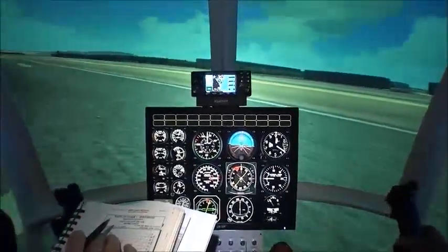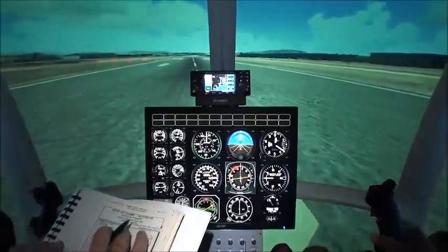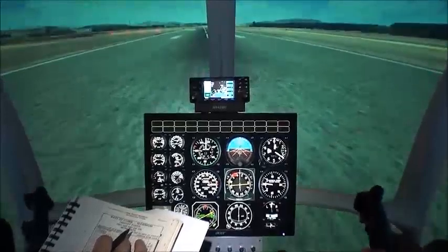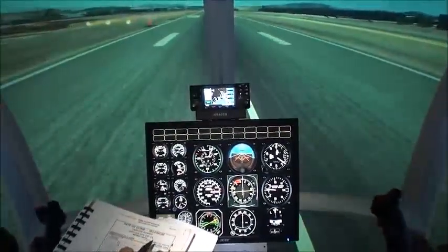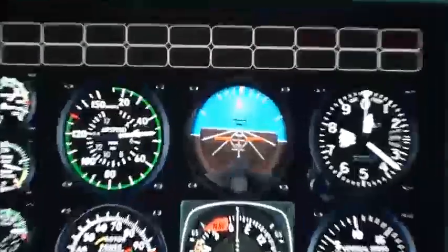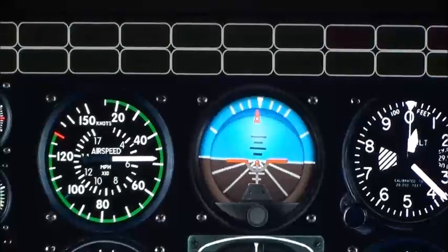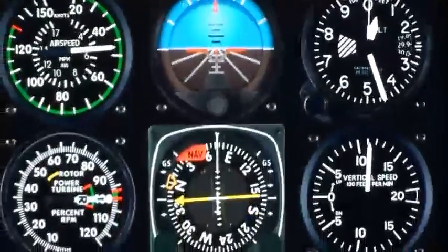Now you just turn it around and say, go down the runway. Okay, here we go. So we're going to put takeoff power in it. We're going to go to 52 knots and hold that and see if the rate of climb is about 1,400 feet a minute, which is what the book says it will do.